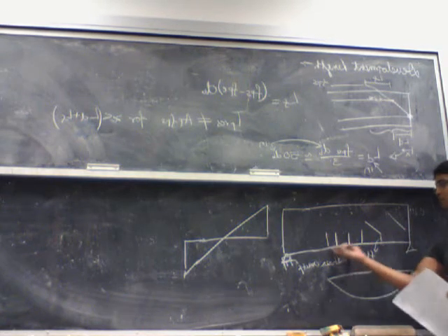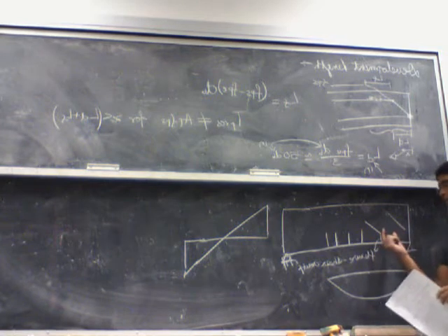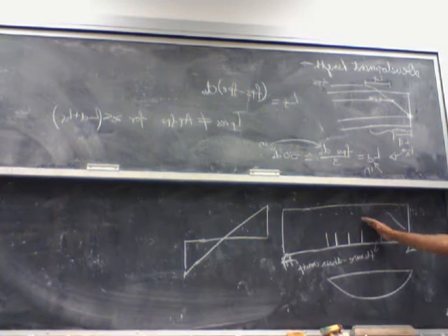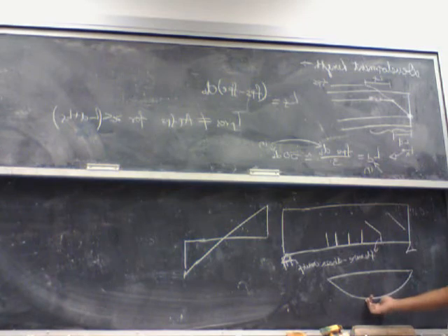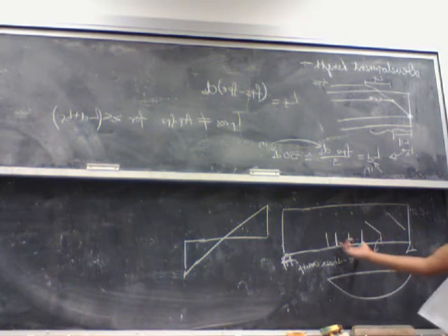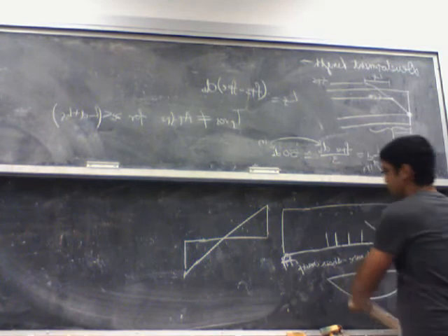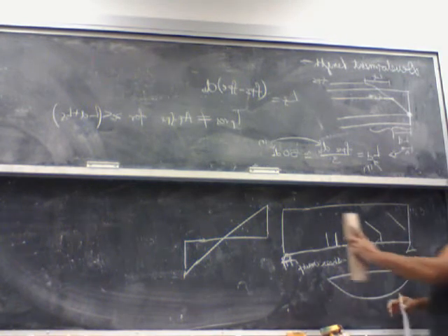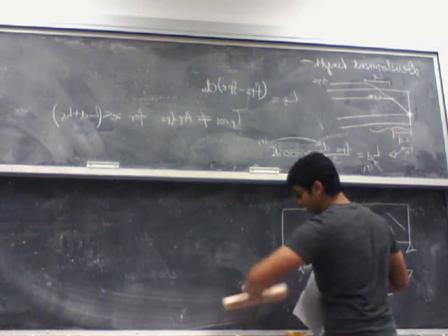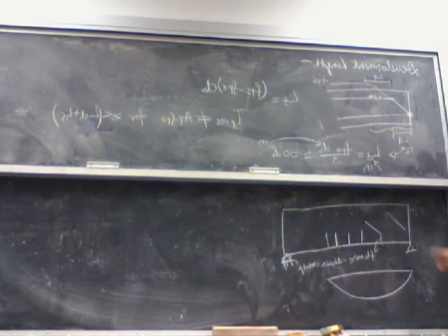Between the support and the midspan, it's a combination of both the flexure cracks and the shear cracks. And near the midspan, it's dominated by the moment, so you will only see moment cracks. So now what we need to do is find out the shear capacity of the concrete itself. We have a different formula for both the shear crack and the flexure shear crack.